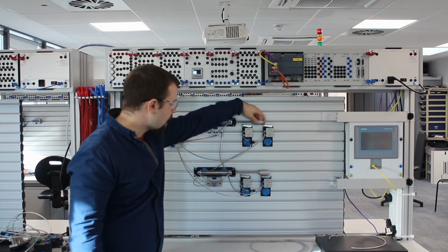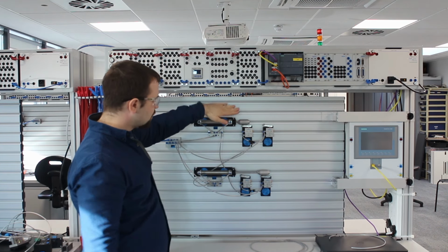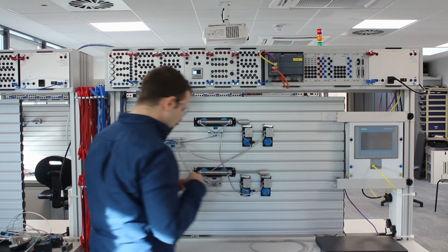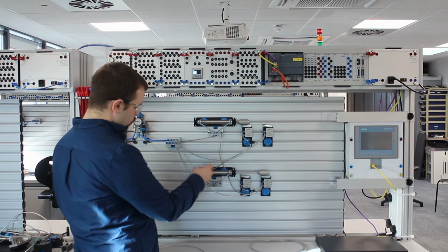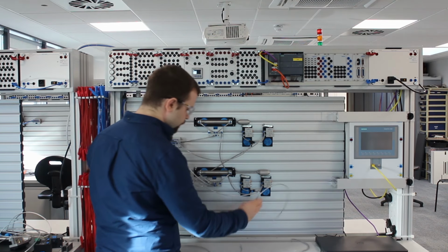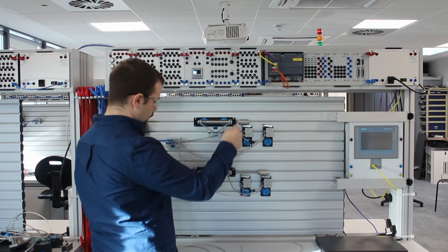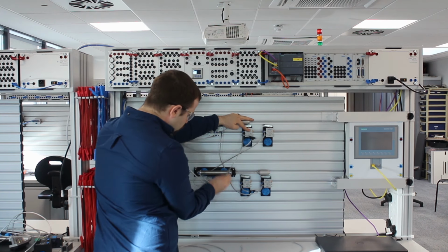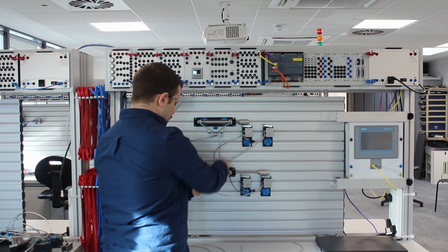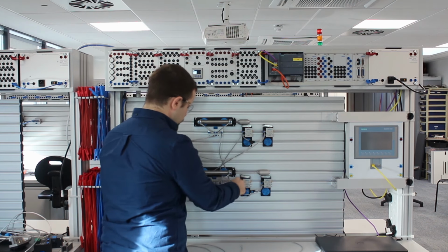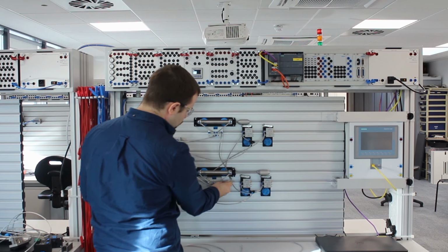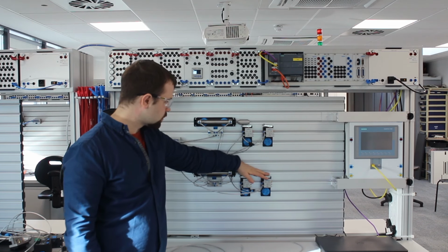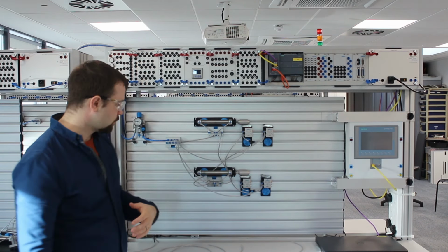This will cause this to come back, so we get to here. And we now need to use this switch to trigger this to come back. So, take a pipe. Probably a slightly shorter one might do. No, I think you'll have to do this one. Here we go. So, 2 from the A- position to 1/2. Again, going to go through the back of the cylinder just to keep it tidy. To 1/2 on this valve. That will cause this to retract. And now the cycle is ready to start again.